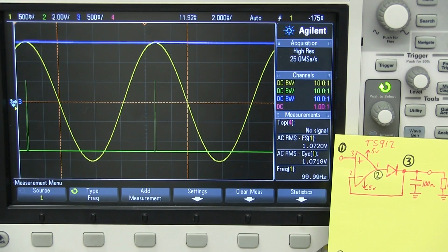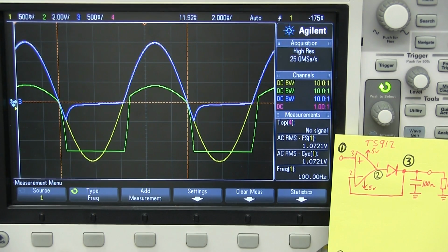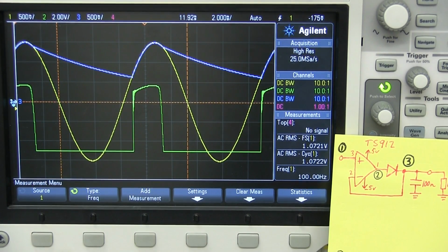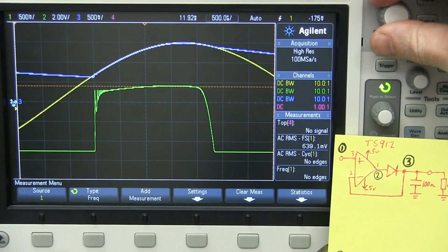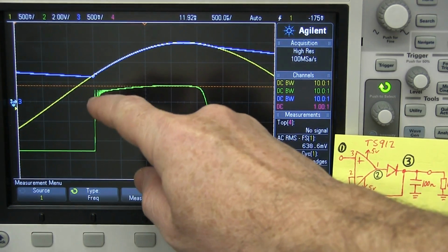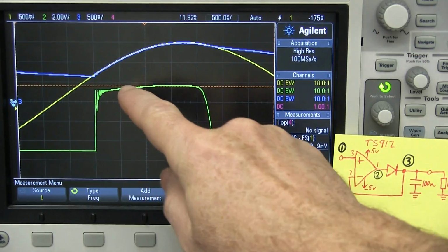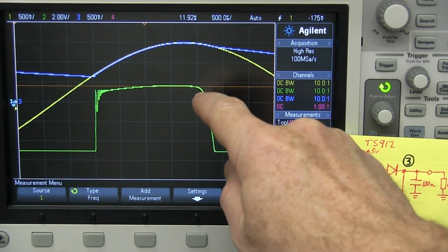So as you can see, you really do want to try and keep the value of this capacitance fairly low in order to get the performance that you're after, but then you need a real high impedance load over here. So at the moment I've got 100N in there, and if I change that 100N back to, ta-da, a 1N, then we're following that much more nicely, and the op amp is only going berserk at the start here, and then it's tracking the input very nicely around here.